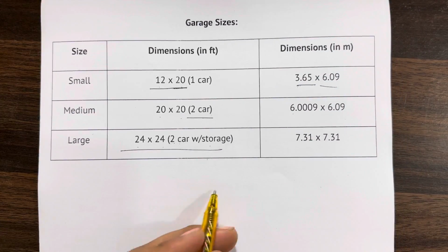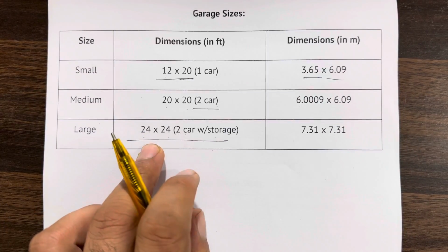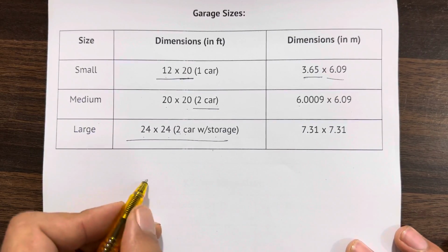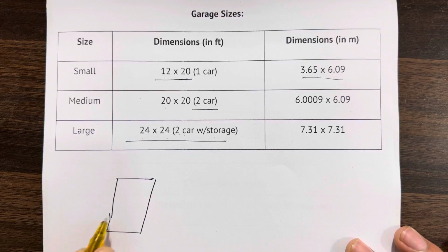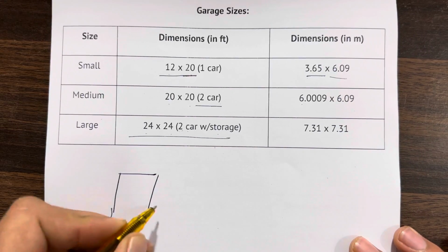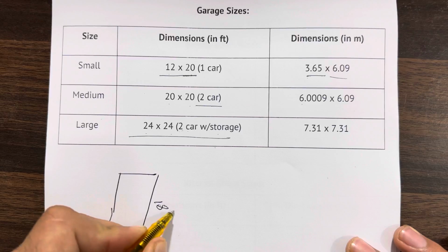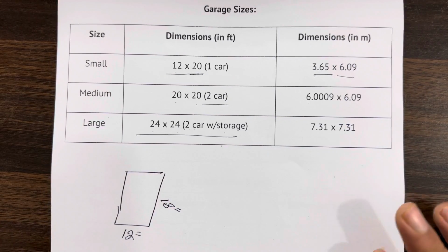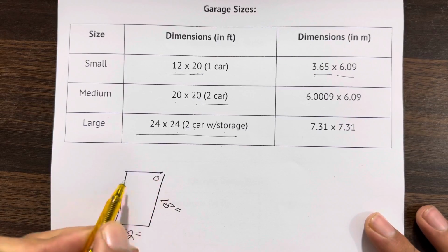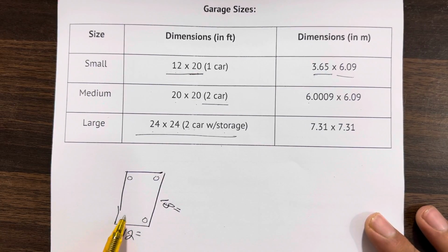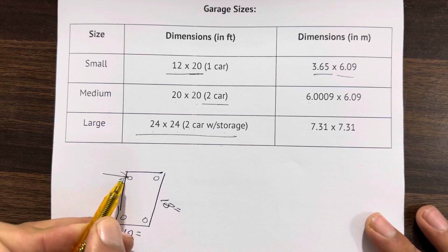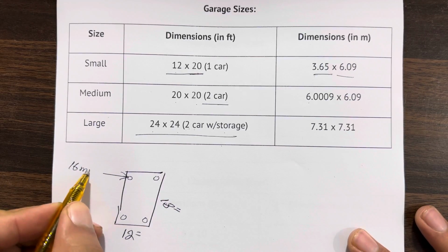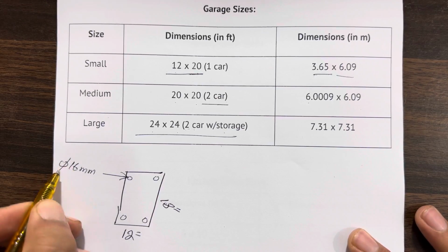So now let me guide you for the 24 by 24 feet garage. Here you should provide the size of column which should not be less than 12 by 18 inches. So it should be the size of column for 24 by 24 feet span. And use here 8 numbers of steel rods, and corner steel rods, main bars or longitudinal bars dia should not be less than 16 millimeter, 4 numbers.